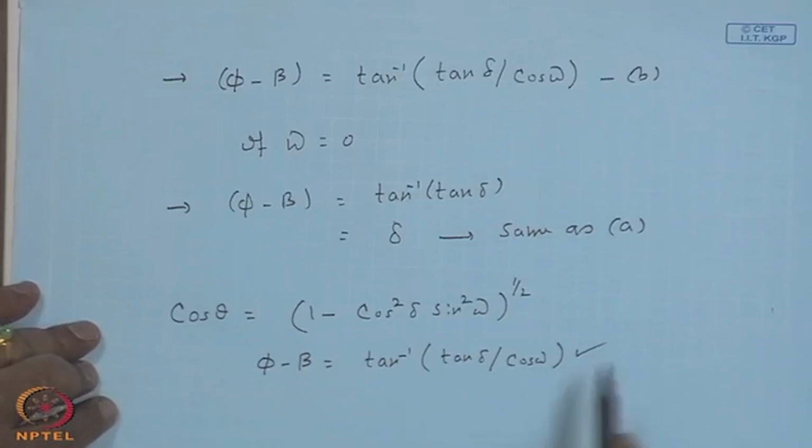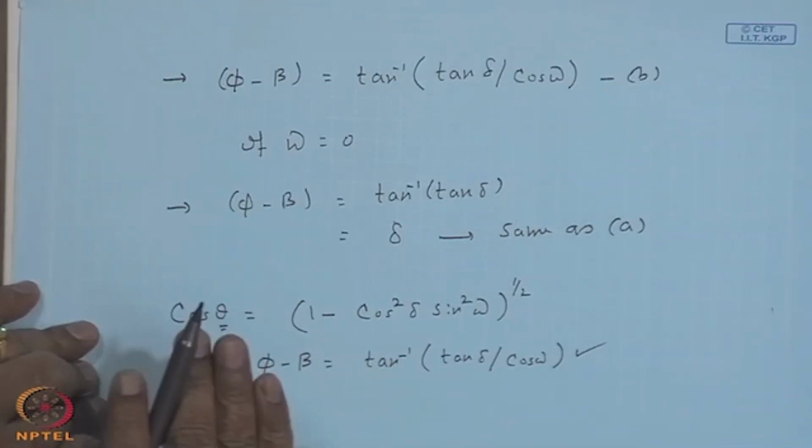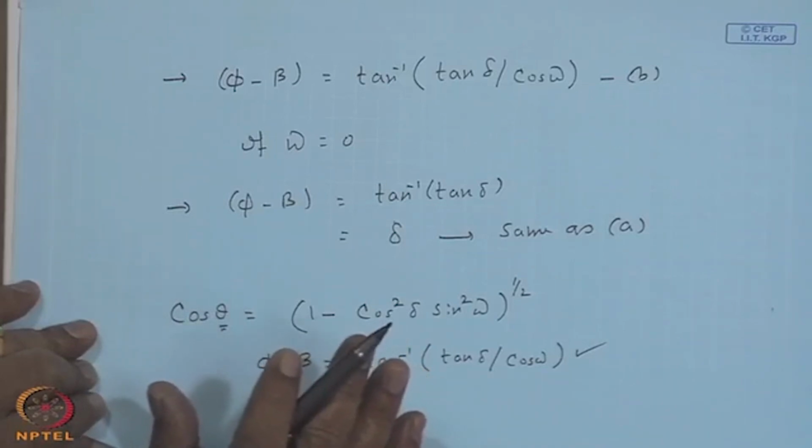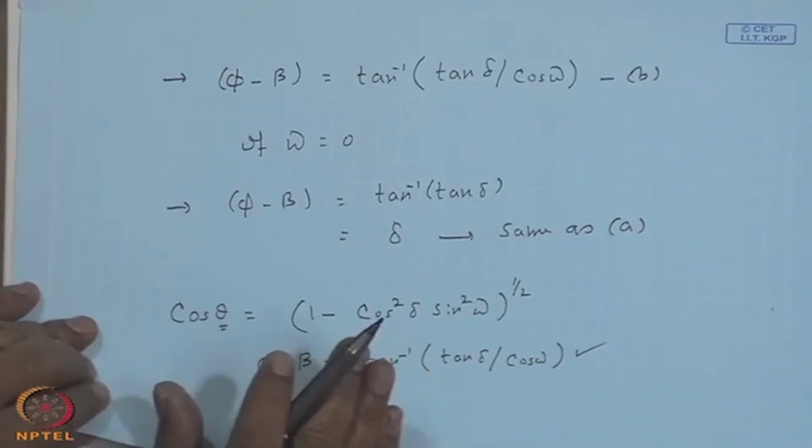In other words, it swivels around the east-west axis such that beta is adjusted with this equation, and your theta is a minimum. Theta will be 0 only at noon time, but theta will not be 0 at other times for this mode of tracking.